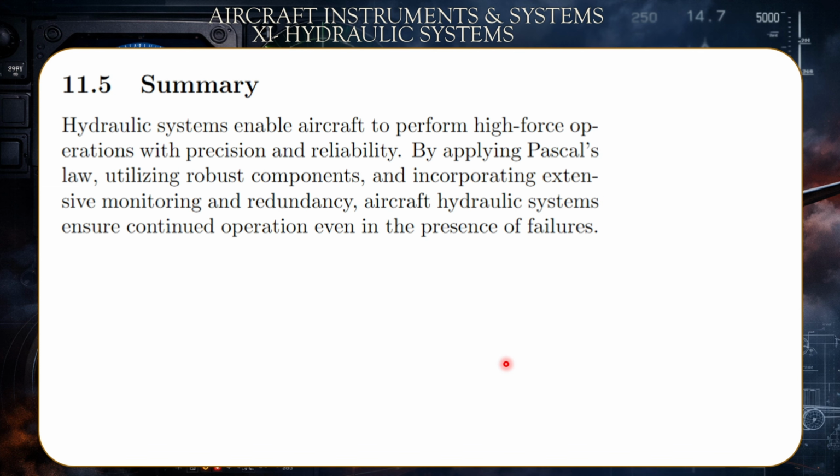Another type of sensor would be one that changes capacitance based on the fluid that is available between the armatures, the positively charged and negatively charged armature. When the fluid drops, the absence of the hydraulic fluid and the presence of air between the armatures would alter the value of capacitance.